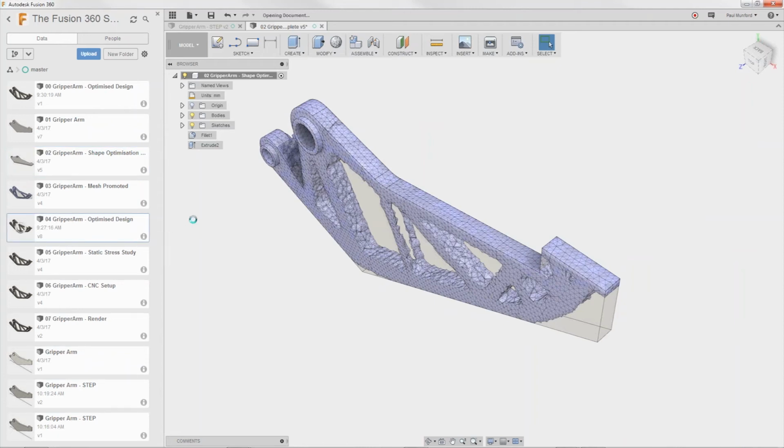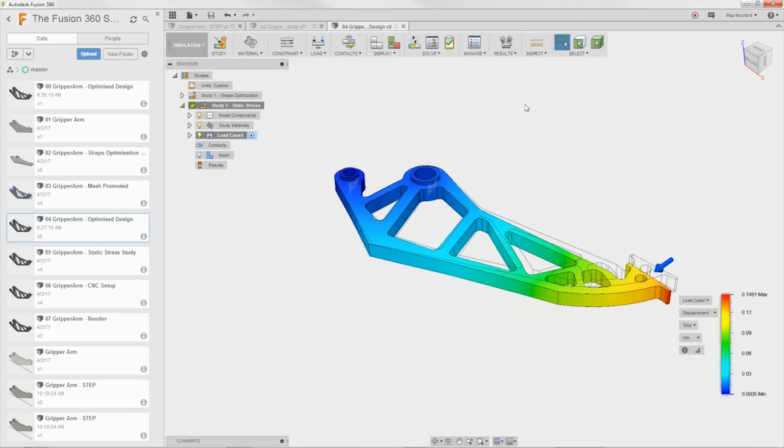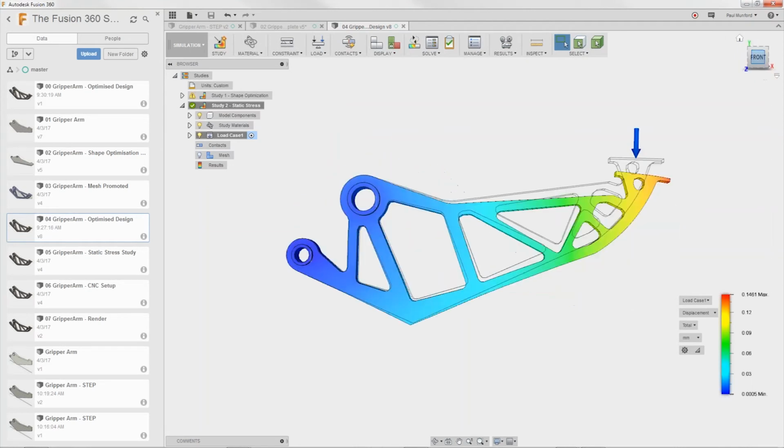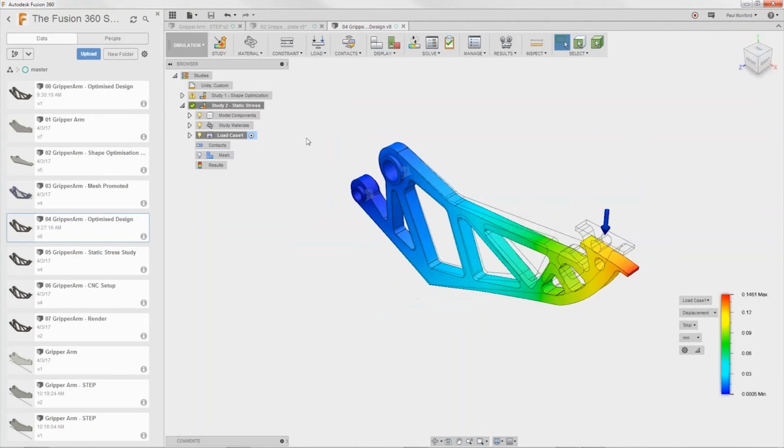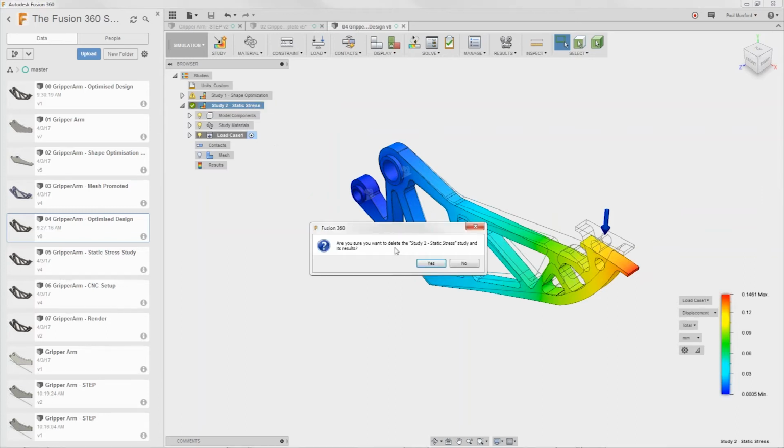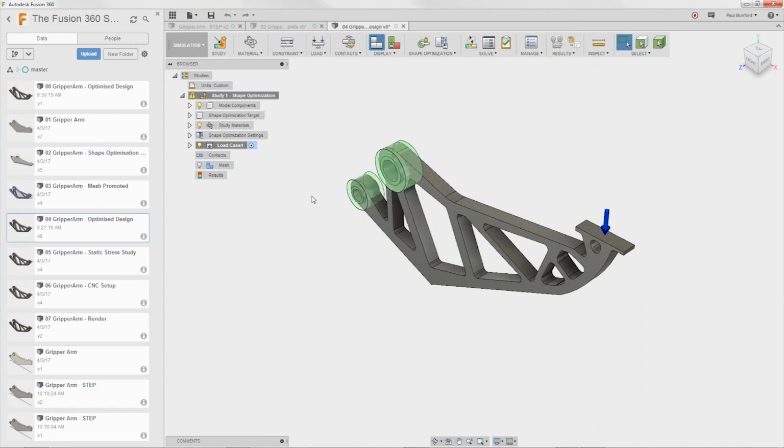I can use my project tool in the sketch, so I'm going to go to project include and project, and I'll just begin by projecting in these 2 circular areas here. I'll say OK to that, and then I could draw out a circle, and I can reference the mesh edges to make sure these circles are the right size, and then I could start sketching in some lines. So I'll just take a line down to here and up to here, and I'm not going to sketch out the whole thing, but I'll just finish this sketch, just cut this away.